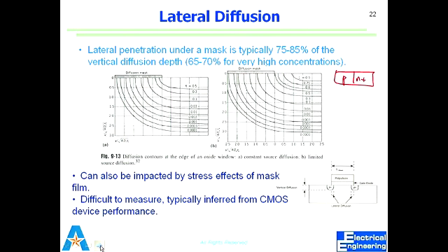Everything else stays the same. Your mass material is the same. Your thickness would be different, because in implantation now they can travel through certain thickness. So unlike diffusion, where it can withstand 99% of the dopants out because they're just diffusing, in ion implantation they can penetrate through.